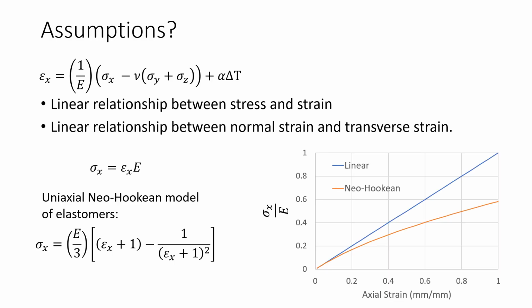By comparing the linear and neo-Hookean models, we can see that they are very similar in the strain range less than about 10%, and become increasingly different at larger strains. For the strains up to 20% that we've been discussing, we might expect that our answers are a little different than what we would find experimentally, because our physical system doesn't quite align with the assumptions of our equations.